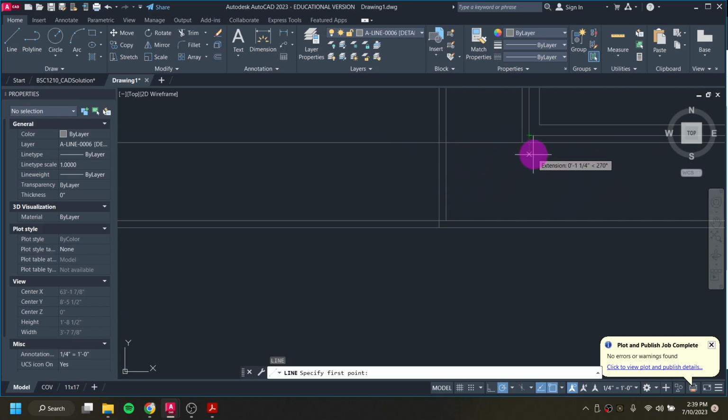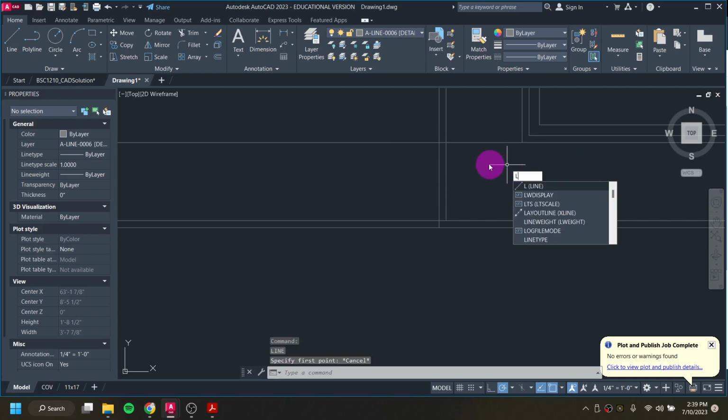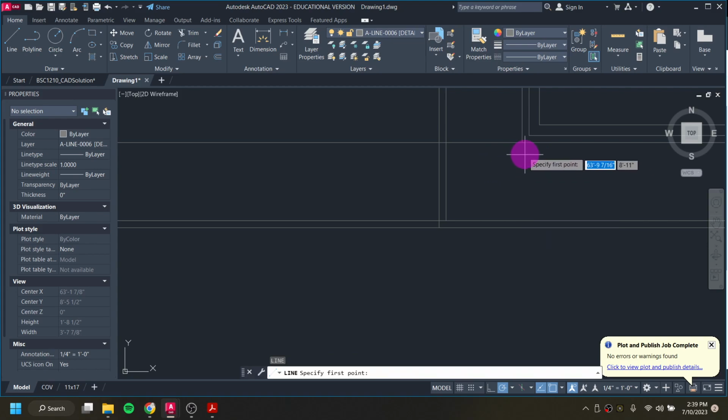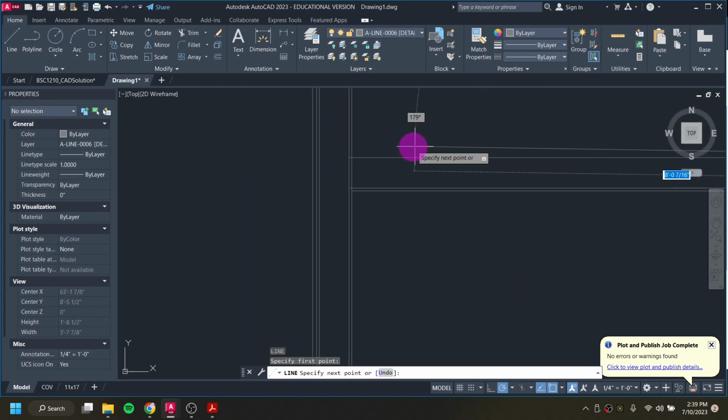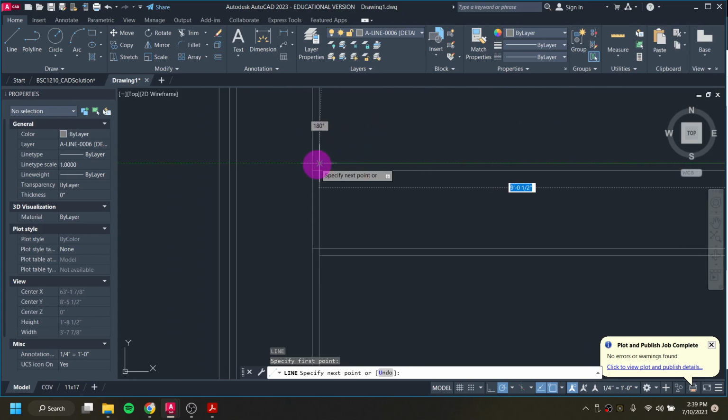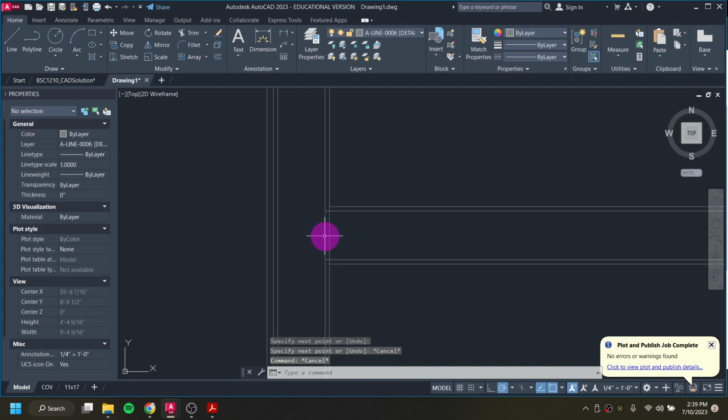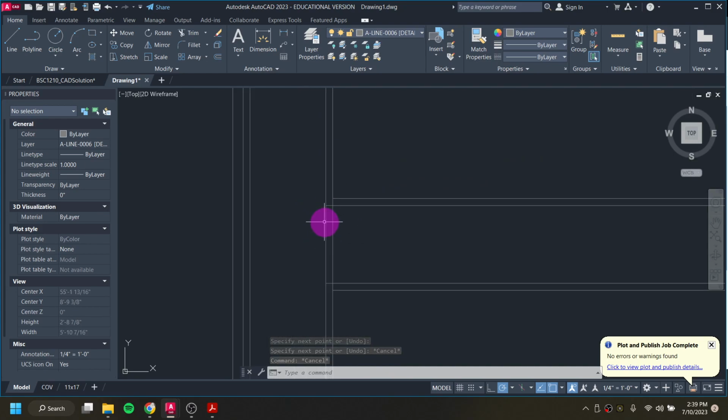And what I'm going to do is when I go into the line tool, L, enter, I'm going to hover over that to track it, just so I have less that I need to erase or trim. Next, I'm going to clean up this connection by just trimming it.